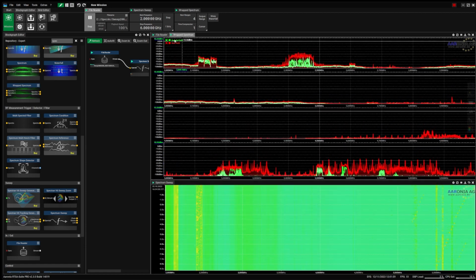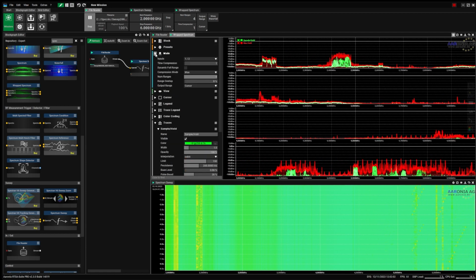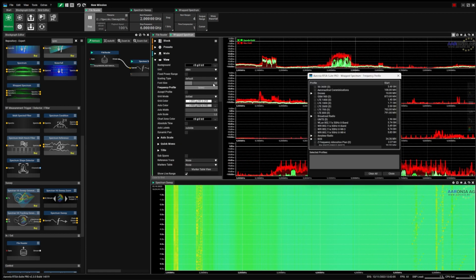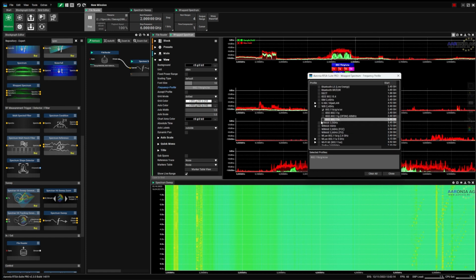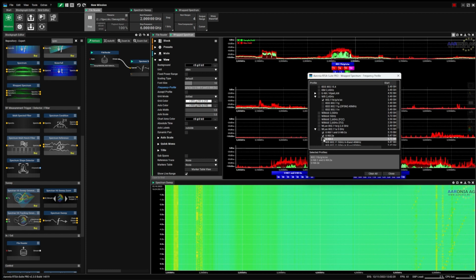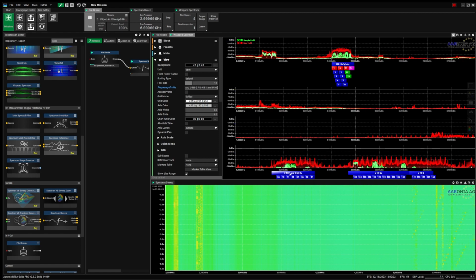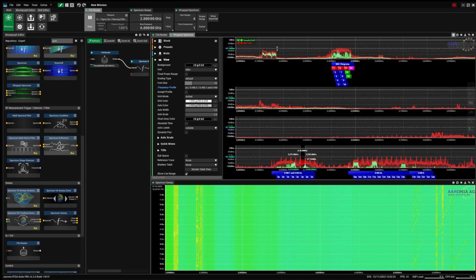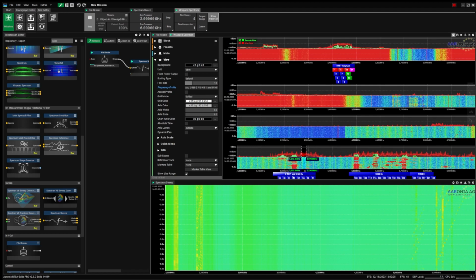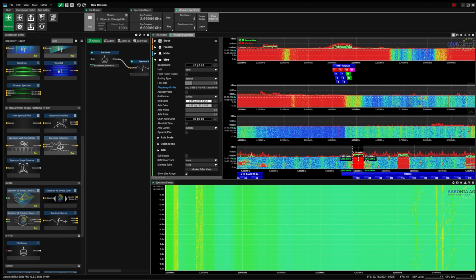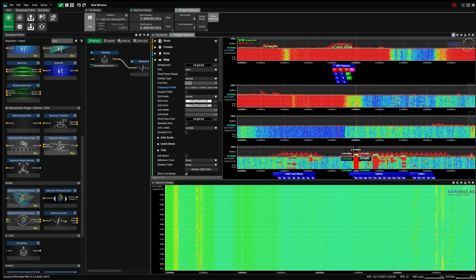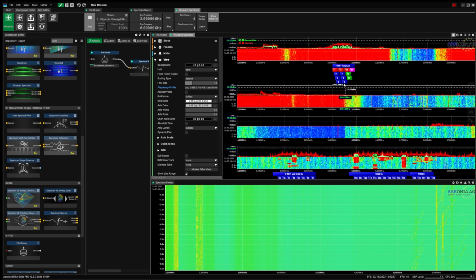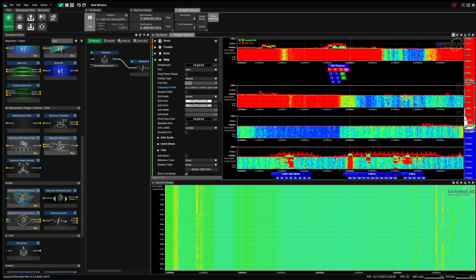This is quite fantastic. You can also do the same thing here by adding frequency profiles. For example, for wireless networks, we can add, not Wi-Fi 6, we don't have that here. We can add 2.4, and we can add Uni 1 and 2, Uni 2 extended, and Uni 3. So now we have this here, and you can also add a waterfall. You can see which channel is utilized. You can zoom in, zoom out.